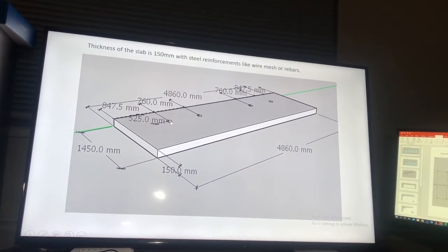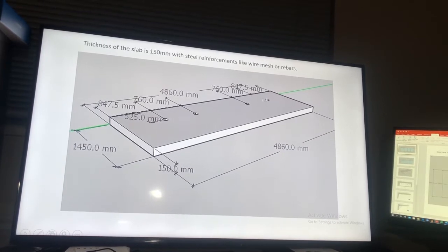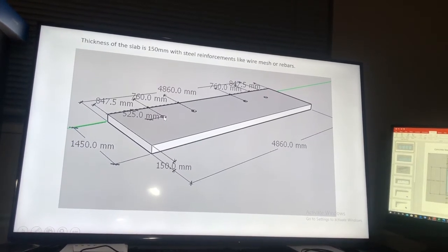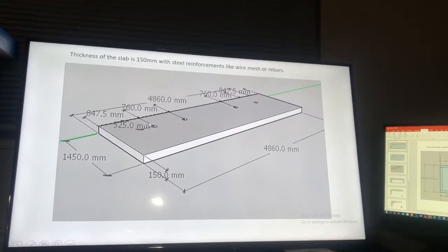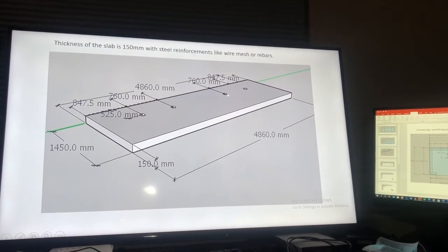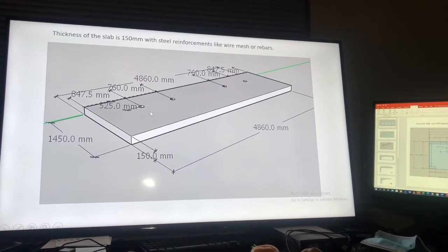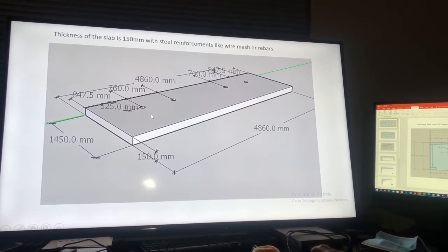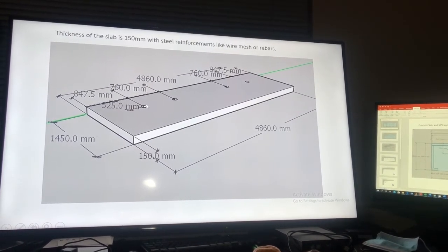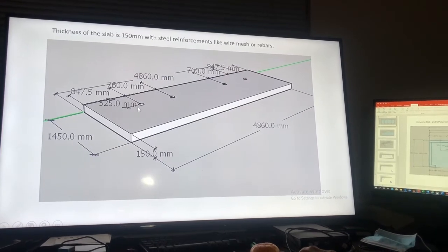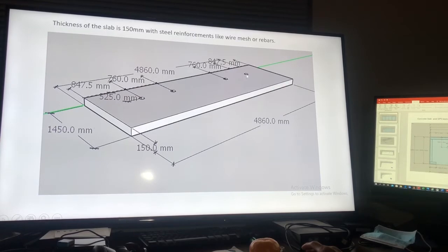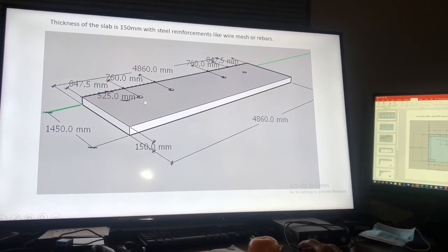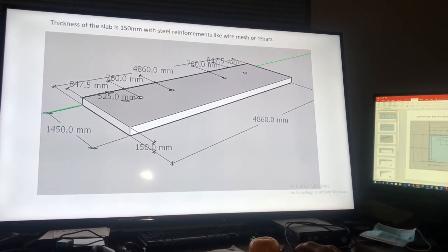And you need to make all the holes for the drain. That's important because you need to create the space when you pour it, or place the plumbing already here, so you have the space ready, or the plumbing stub, before the pouring of the slab.